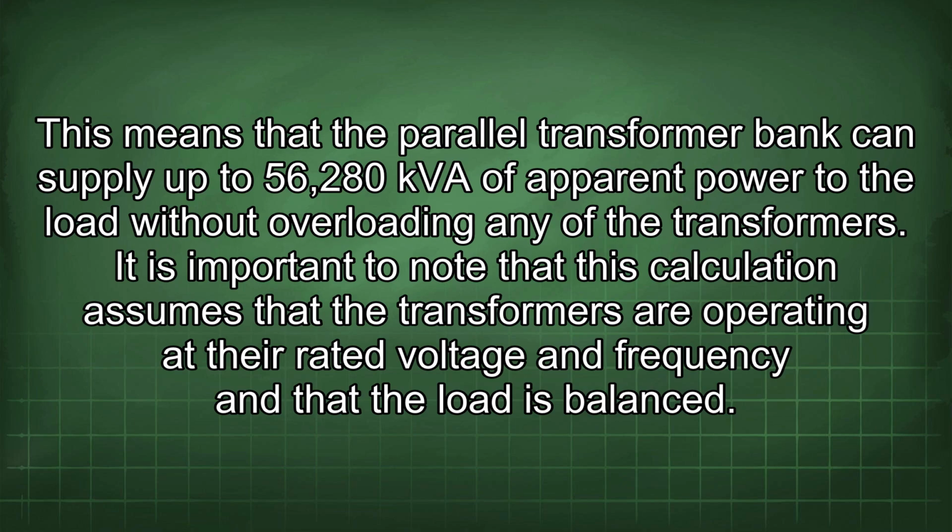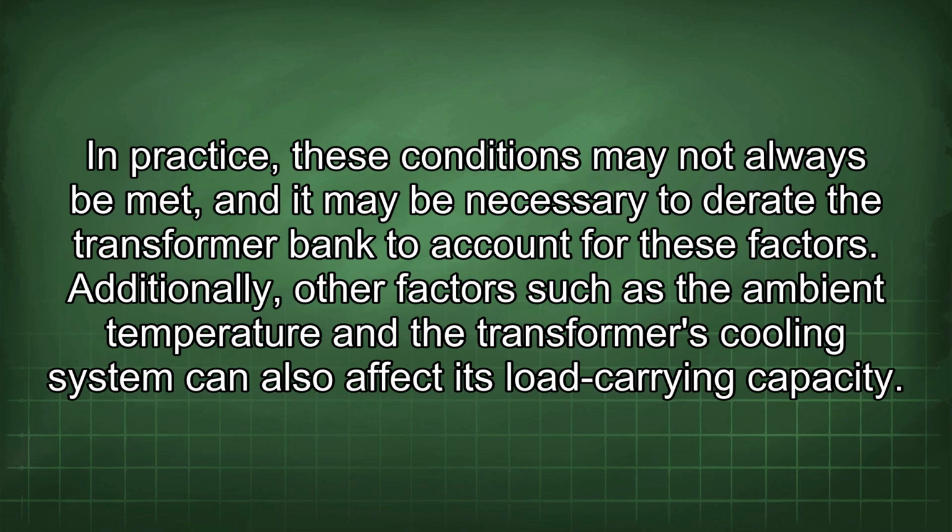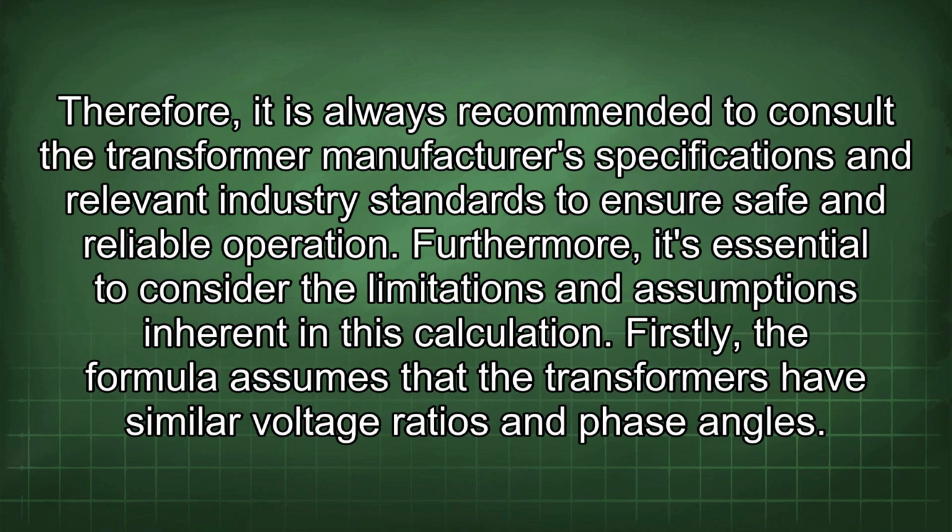It is important to note that this calculation assumes that the transformers are operating at their rated voltage and frequency and that the load is balanced. In practice, these conditions may not always be met, and it may be necessary to derate the transformer bank to account for these factors. Additionally, other factors such as the ambient temperature and the transformer's cooling system can also affect its load carrying capacity. Therefore, it is always recommended to consult the transformer manufacturer's specifications and relevant industry standards to ensure safe and reliable operation.